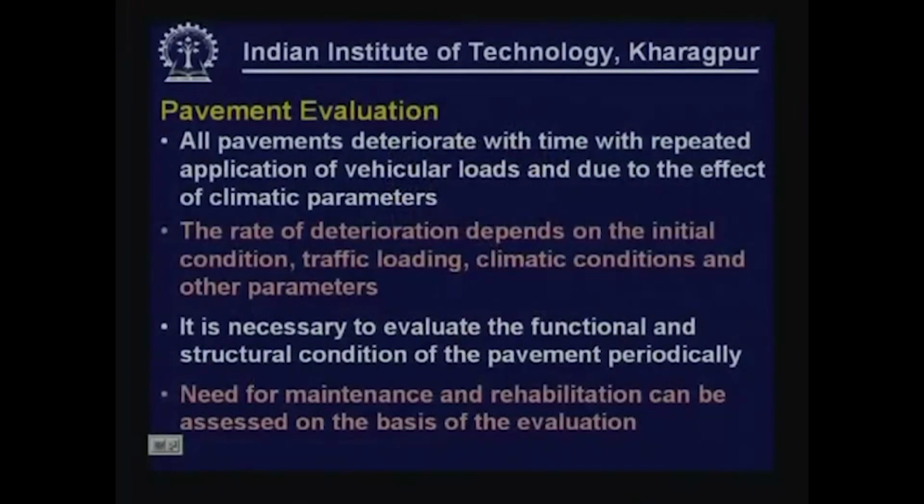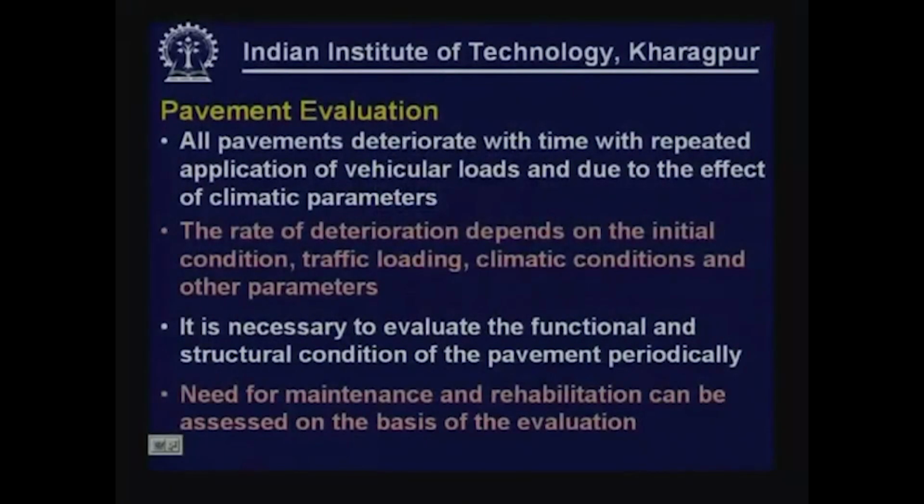It is also necessary to evaluate the functional and structural condition of the pavement periodically. As I just indicated, we should be able to assess the structural condition and functional condition of the pavement periodically and decide whether the pavement requires any maintenance, major rehabilitation or even reconstruction. Need for maintenance and rehabilitation can be assessed on the basis of the evaluation that we carry out.